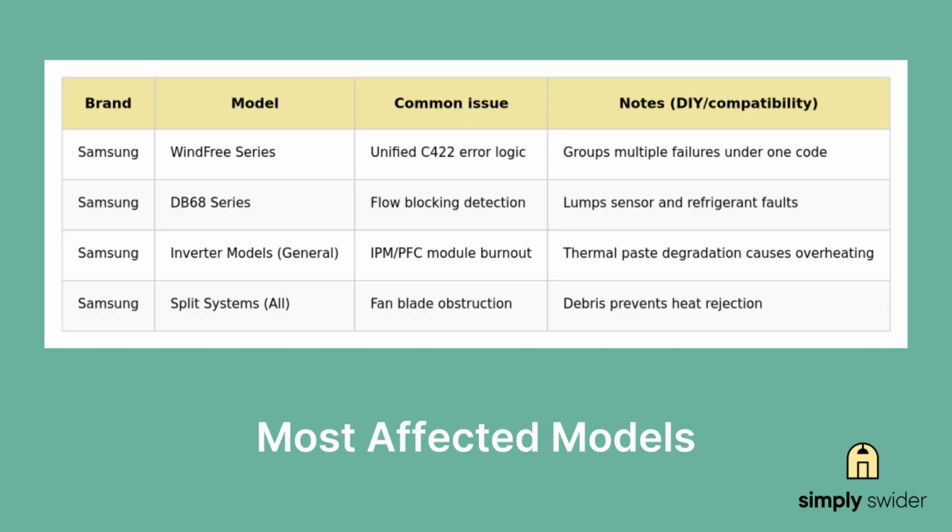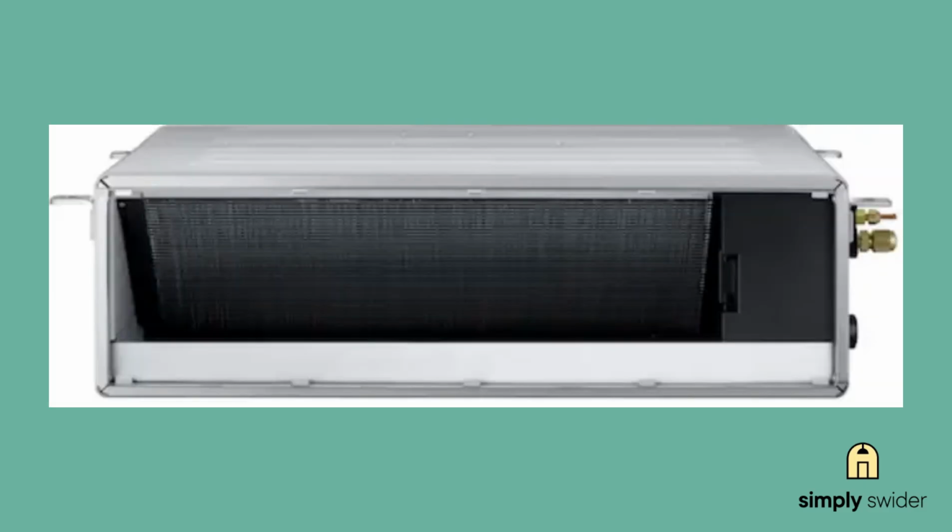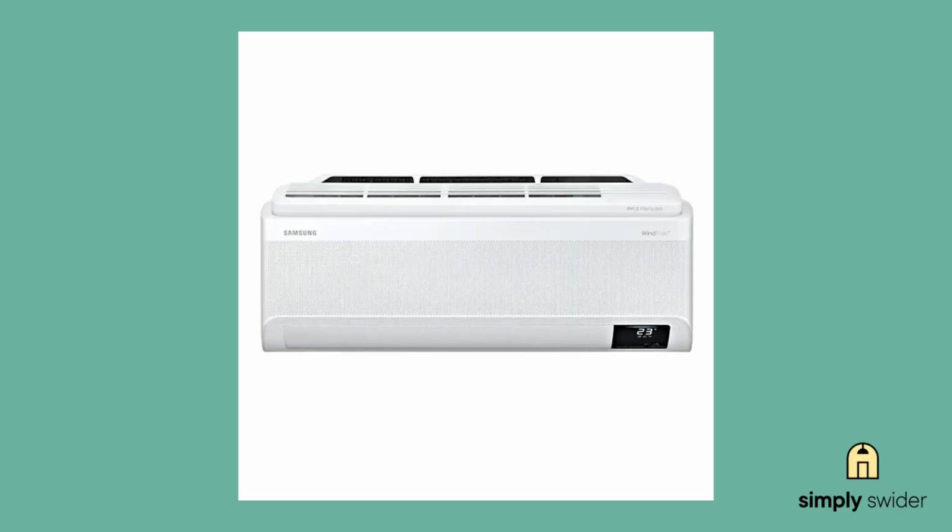Now you can see on the screen right now the most common Samsung models that deal with C422 errors. The WindFree and DB68 series are particularly prone to this because of how Samsung designed their unified error logic. They lump leaks, valve closures, and sensor faults all under the same code. The inverter models in general have issues with IPM module burnout due to thermal paste degradation over time. Maybe you'll spot your model up there. If so, you're definitely not alone with this problem.